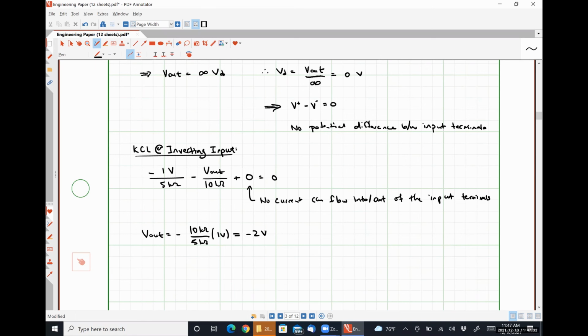So what's the difference in this analysis using the ideal model versus the analysis that we did using the practical model? About 0.00006 volts. Yeah. So practically no real difference whatsoever. As it turns out, we have to design a pretty poor op amp to make the ideal op amp rules not apply in a negative feedback situation, okay?